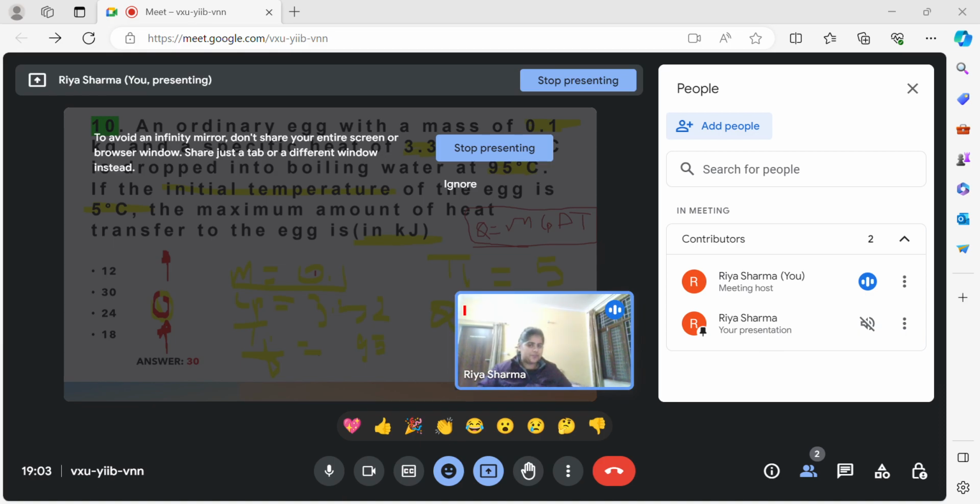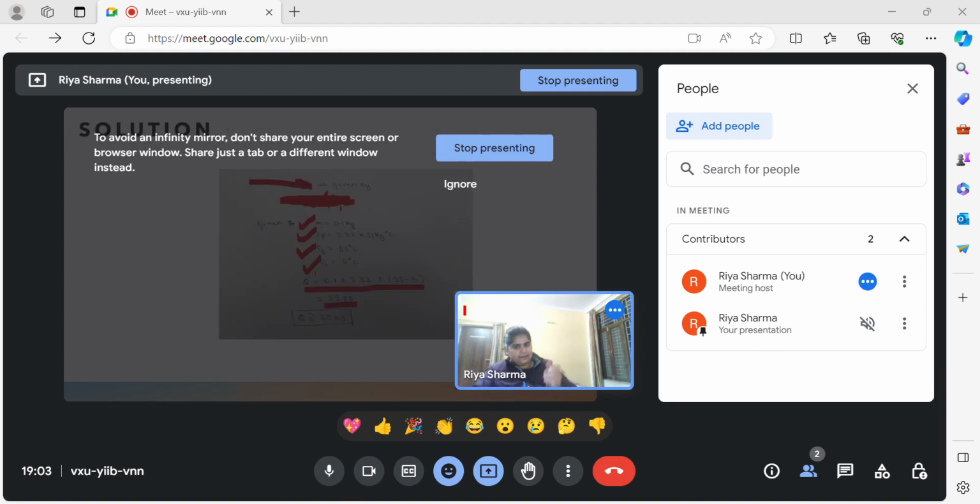Here all the options have been given as positive. If I had given one option as negative, can heat be negative here? Just think before you try to apply this formula. The basic formula is mCp delta T. You should always remember this, because when there is no phase change happening, the heat transfer on any object or in any quantity is given by mCp delta T. You just have to put in the values.